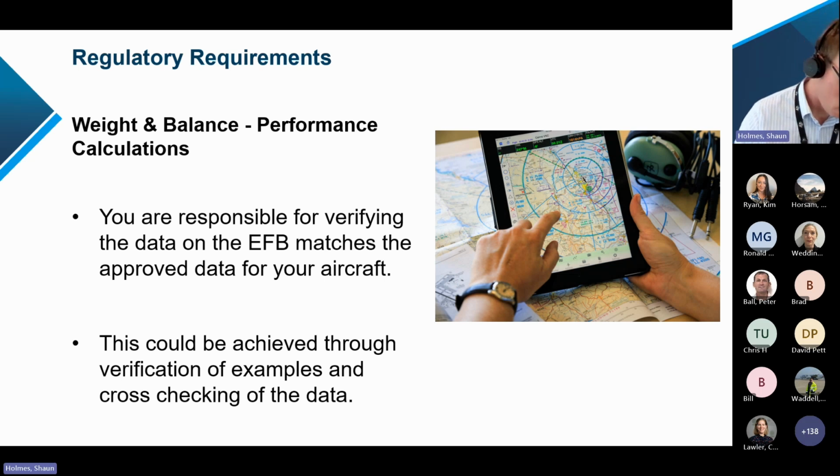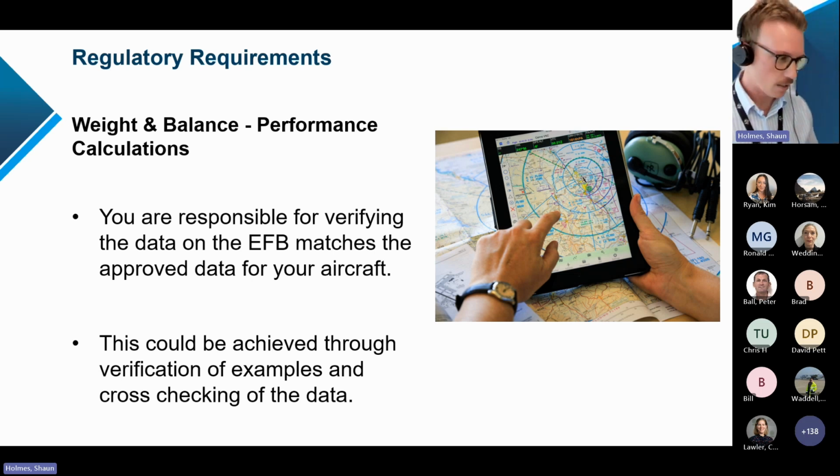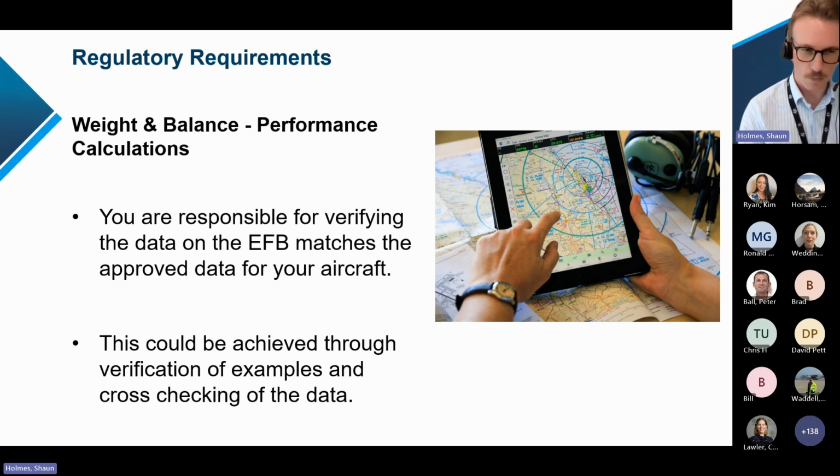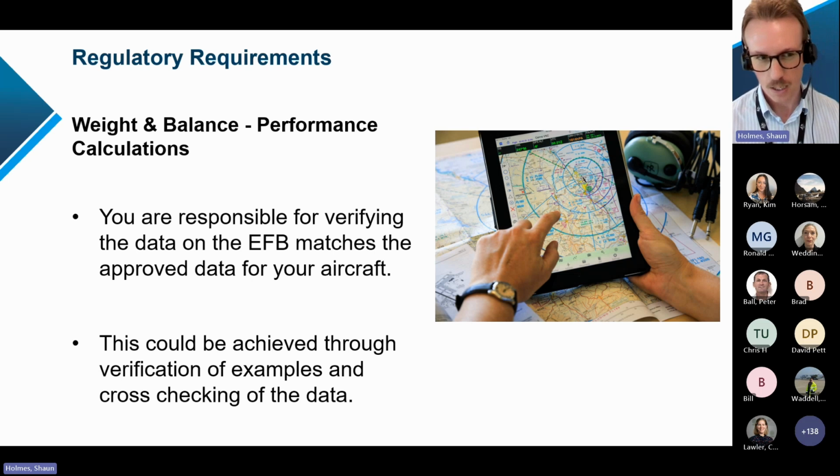Now, I'm sure some of you are wondering, what about if I wanted to use my EFB for weight and balance or performance calculation? So again, I will split this for a Part 91 private operation. As the pilot in command, you are responsible, if using the EFB, for ensuring that the data or the information that the EFB produces matches the approved data for the aircraft.